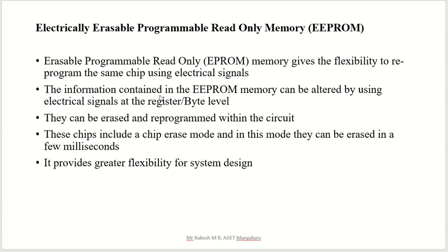The information contained in the EEPROM memory can be altered by using electrical signal at the register or byte level. They can be erased and reprogrammed within the circuit. You can erase that or reprogram by using electrical signal. That is the main point here.